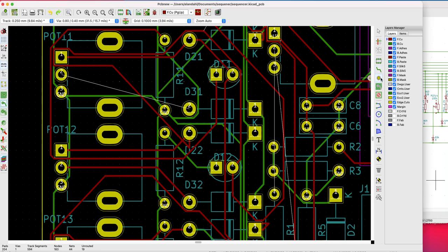So I'm going to grab a via, which is this circular tool, and think about running the trace out in green to this point over the red line, and then from red we'll go across over these green ones down to that pad. So I'll stick my via there, go back to the routing tool, put it on the bottom green color.